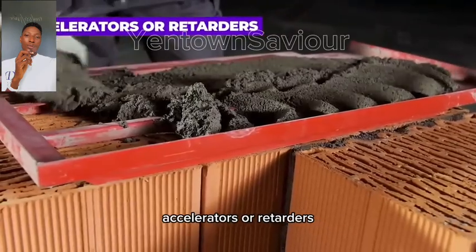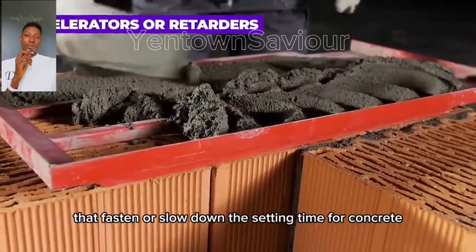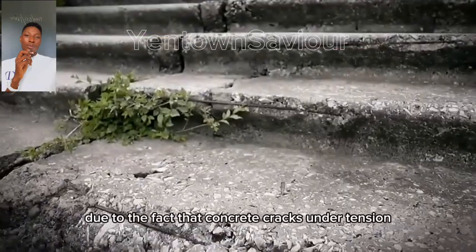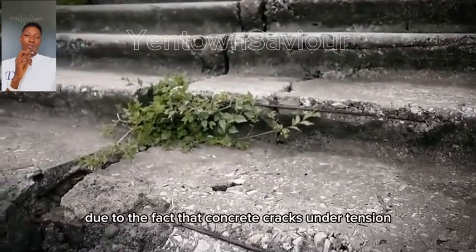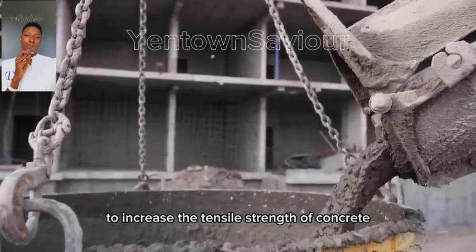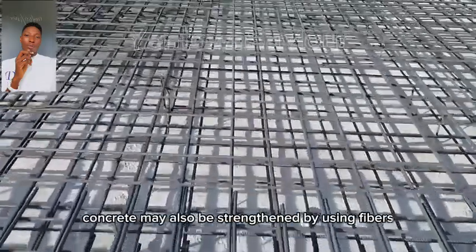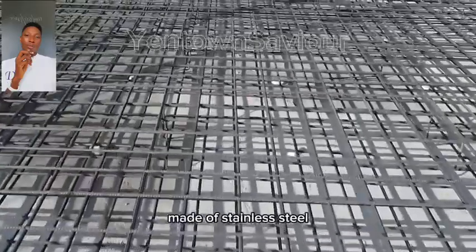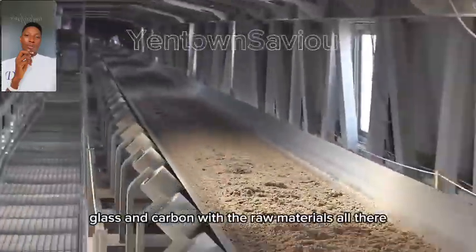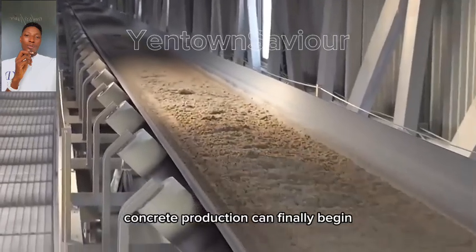Accelerators or retarders are another type of admixture that speed up or slow down the setting time for concrete. Due to the fact that concrete cracks under tension, many chemical additives have been developed to increase the tensile strength of concrete. Concrete may also be strengthened by using fibers made of stainless steel, glass, and carbon. With the raw materials all there, concrete production can finally begin.